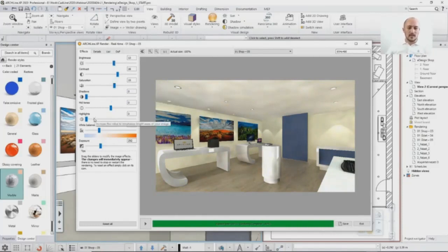Don't overdo it. And shadows, midtones, and highlights: shadows are more like dark tones, because if I dial this up, as you can see, all dark areas are even darker. So it's not necessarily only the shadows, it is for the dark areas. So you can actually make dark areas stronger, more effective on the render. It's a kind of selective contrast. You can also do something similar with the midtones and something with the highlights. Now highlights are these areas that we already have experienced as very, very bright areas. So in this case, perhaps I don't need to change that, but again, you can change that.